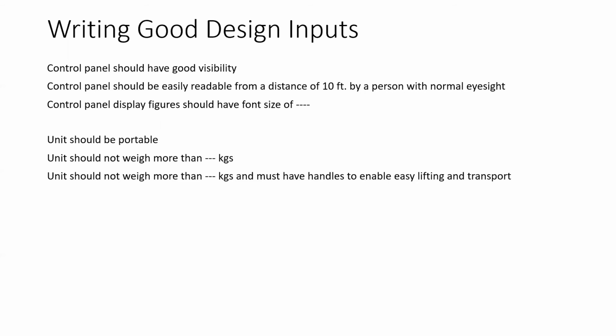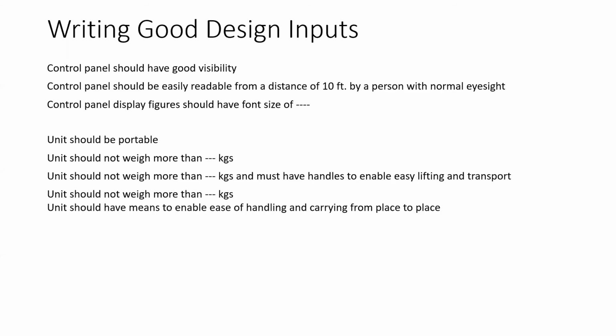Okay, should be portable, fine, but not very easy to verify. For example, a well-built individual may be able to easily carry the device, but a female nurse who doesn't have the same capacity to lift weight will not be able to easily handle the device. So again, it's vague. Should not weigh more than so many kilos. Yeah, that's a lot better. And should not weigh more than so many kilos and must have handles to enable easy lifting and transport.